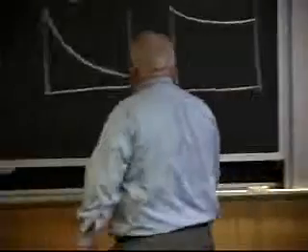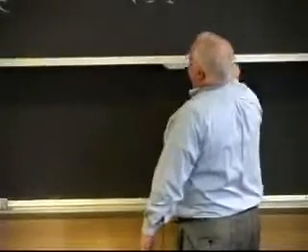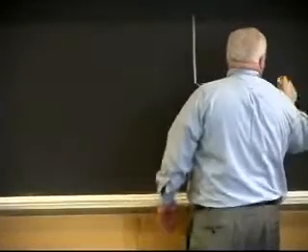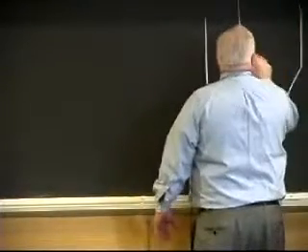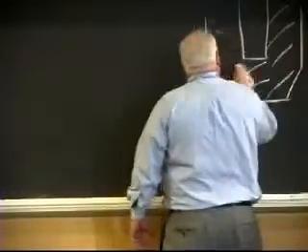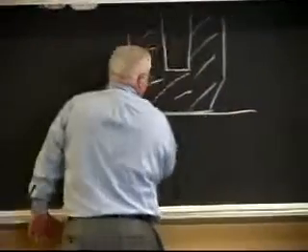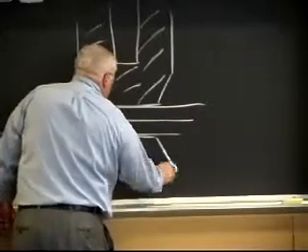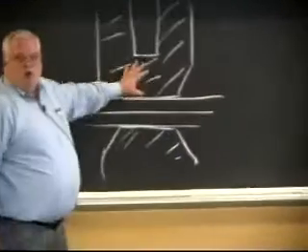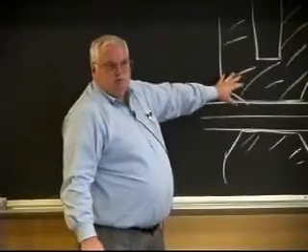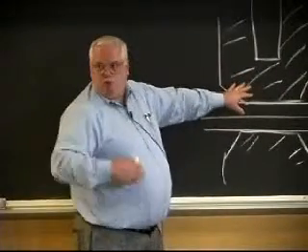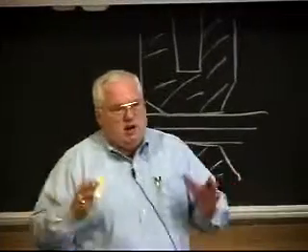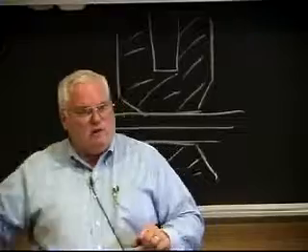For example, one of the homework problems asks: if I've got a resistance spot welding electrode, and this is a water-cooled copper electrode, and I've got a sheet of steel down here, or aluminum, and I've got another electrode underneath it, and I'm going to pass a lot of current through this thing for a 1/10 of a second, let's say. We usually in spot welding talk about cycles of current. We've got 60 hertz current, so a 1/10 of a second is 6 cycles of current.